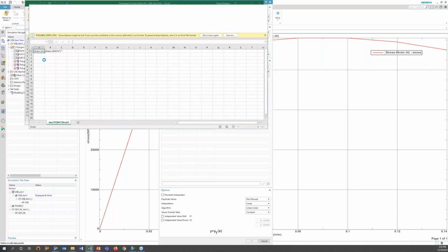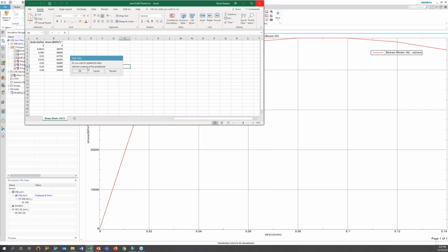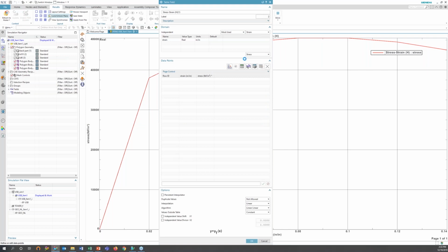And it'll pop this open. Copy. There we go. And there's my values. You need to make sure that your stress and strain value match where you tell it's going to yield. And once this closes down, it should be in here.